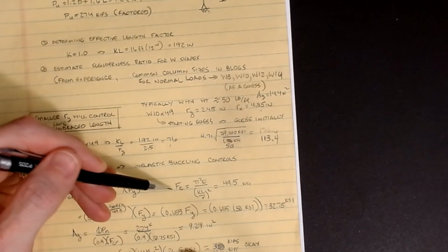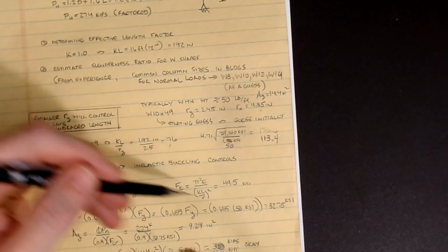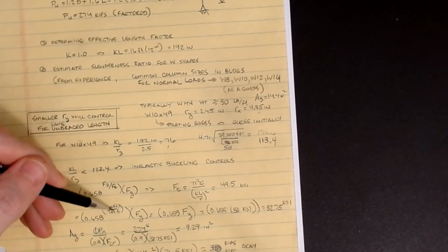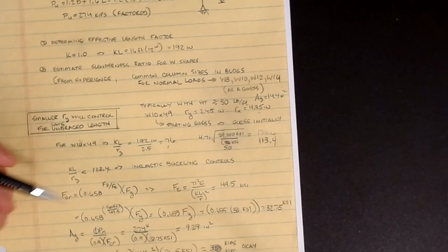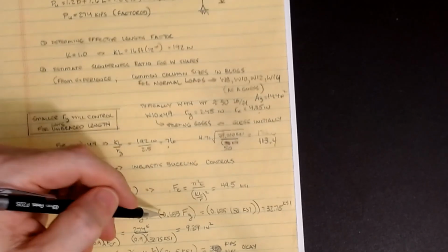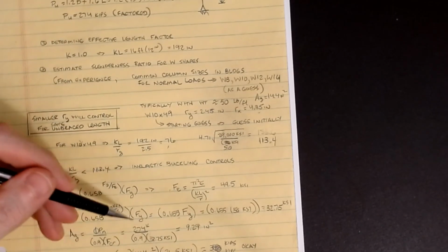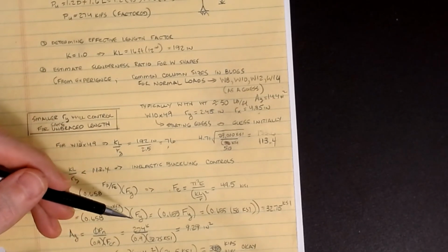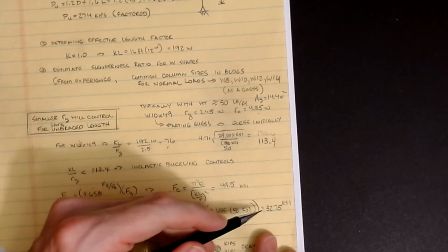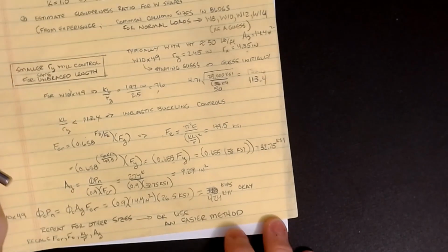If this number comes out greater than the proportional limit for some reason, then you've got to be careful to limit this value. You've got to be a little bit mindful of that. So if I plug all of this in, 50 over 49.5 is basically 1.0, and so this formula becomes 0.658 raised to this quantity times Fy, which is now 0.655. So we're changing the third decimal because we're so close. We're basically getting the full strength out of this. It's just barely on the edge of wanting to buckle. And so if I plug our math in, my critical stress for this is 32.75 KSI. That would be my critical stress for the column.